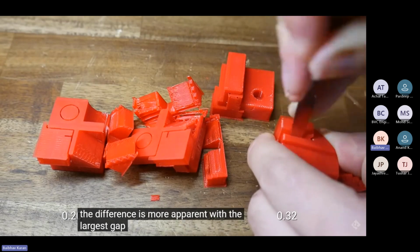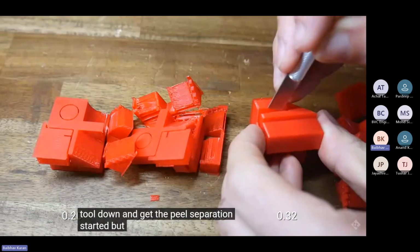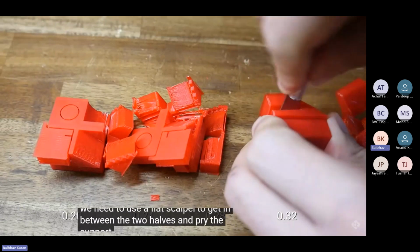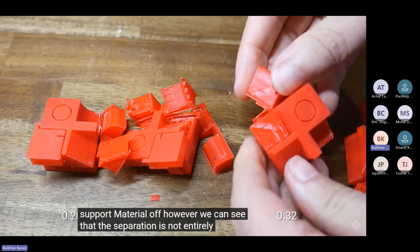With the largest gap, there's room to slide the tool down and get the peel separation started. But from the second largest gap, we need to use a flat scalpel to get in between the two halves and pry the support material off. However, we can see that the separation is not entirely clean.